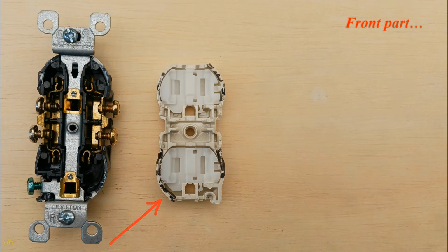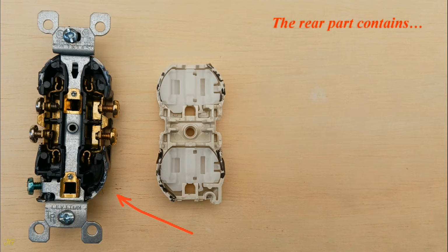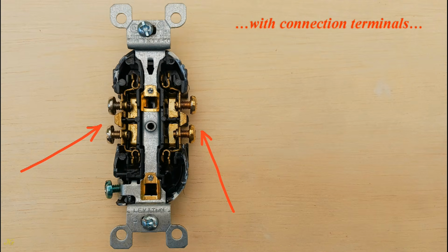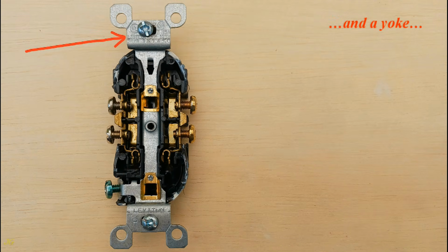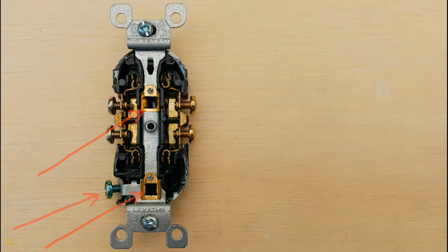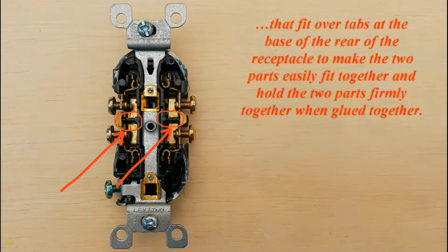Front part has a safety, tamper-resistant mechanism inside its base. The rear part contains female hot contacts with connection terminals, and a yoke with female ground contacts and a ground terminal. Tabs at the base of the front of the receptacle fit over tabs at the base of the rear of the receptacle to make the two parts easily fit together and hold them firmly together when glued together.